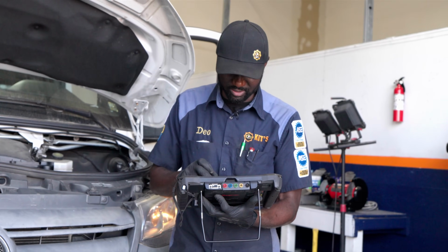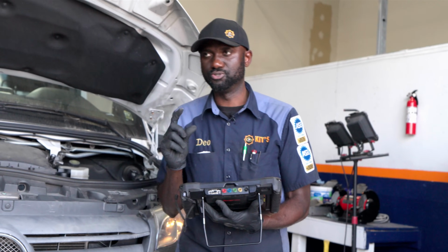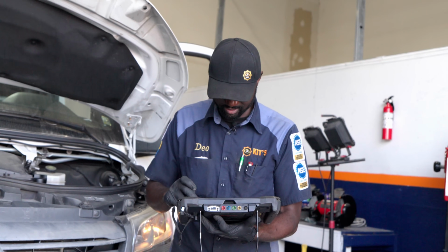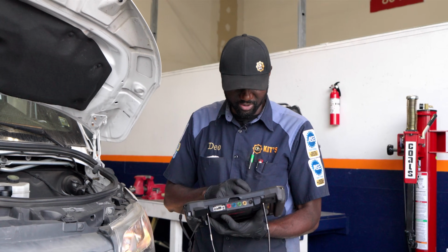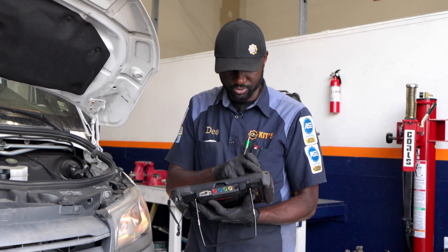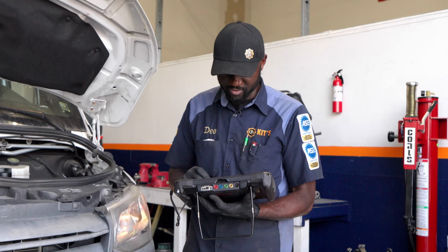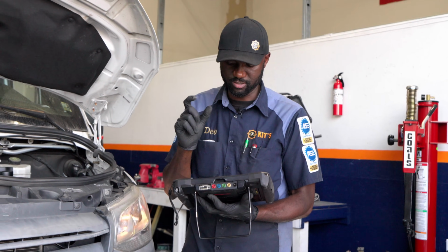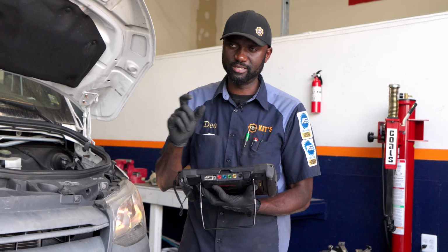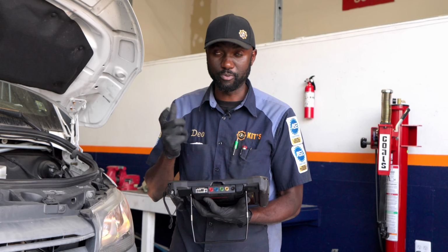P06DA. Let's go to our service info. There's a solenoid there, and that solenoid usually goes bad, or the harness. So let's look up this code. I am familiar with this code, but let's look it up in case some of you have a question. Yeah, so if I remember correctly, the solenoid on the oil pump actually allows the oil pump to build the proper pressure.